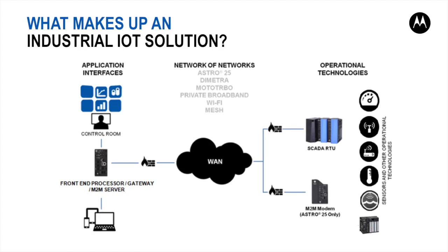The collected data is transported over LMR or other communication network to an HMI via the FEP, which stands for Front-End Processor Gateway. The FEP provides a two-way path to the communication system between the RTU and the IIoT manager host entities. The HMI could be a manned control center or a mobile application devices such as a smartphone or tablets, etc.